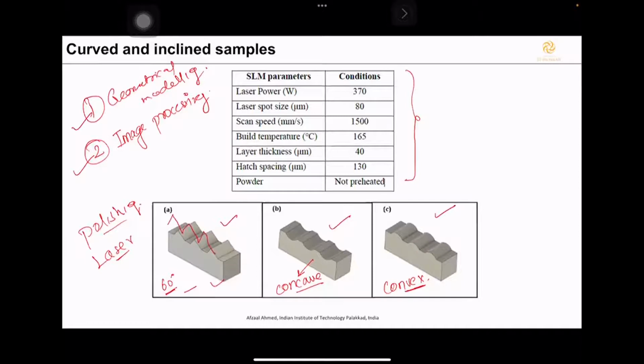If you have a hollow surface like this, the laser power is dependent on the energy incident on the surface. When you move the laser beam on a curved surface, basically the laser is remelting a thin layer on the surface. If you are remelting, the molten material may fall, or may not stay where it is supposed to stay. It may not fall because the cooling rates are very high, but still it may not stay at the place where it is supposed to be.